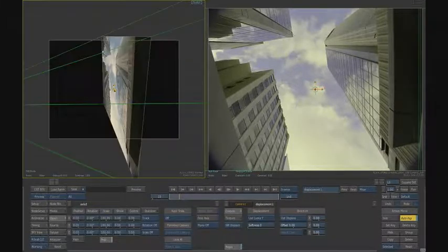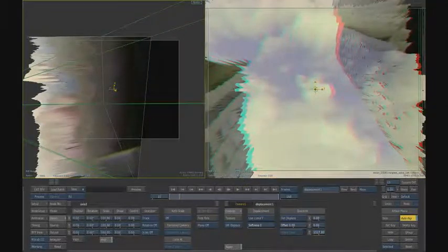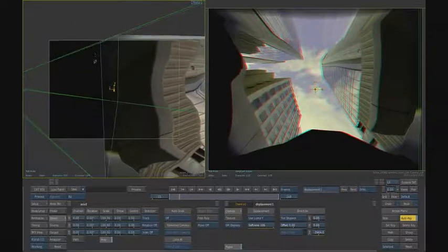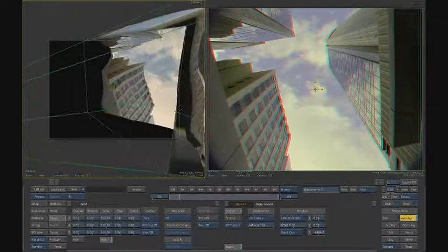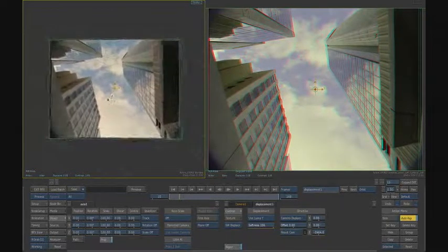And the idea here is to adjust those pixels back and forward, and you'll notice that you do get stereo adjustment or stereo offset. Looking here at the anaglyph view, which is an easy way to view on the web, we have that effect working right off the bat. Let's go ahead and soften it out. But you can see part of the problem here is that we're using flat displacement at this point, so we're not observing the camera frustum. So let's switch to camera-based displacement. That keeps the pixels in exactly the right position from the point of view of the camera.